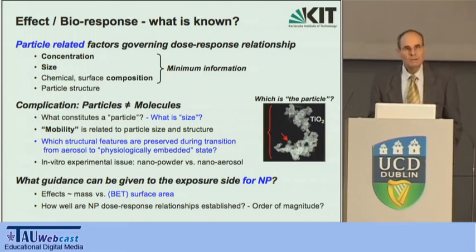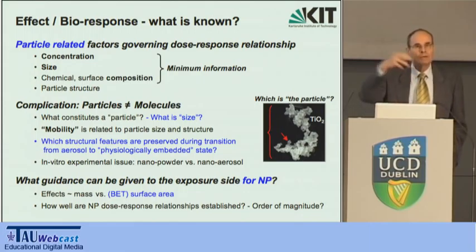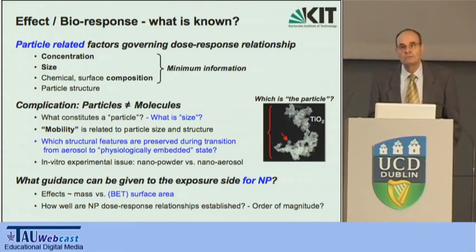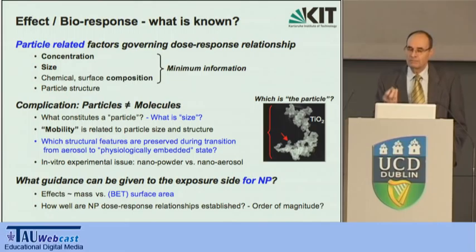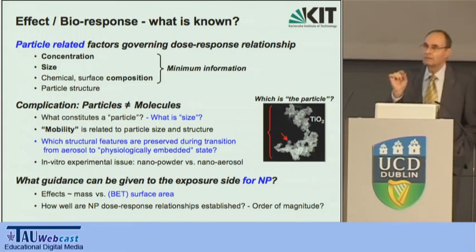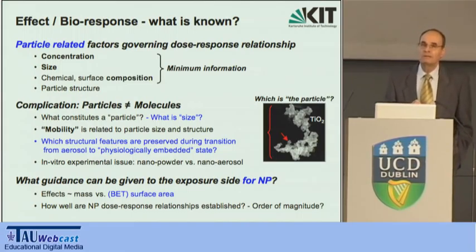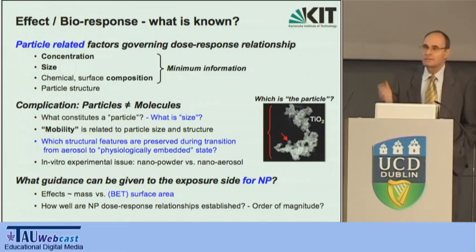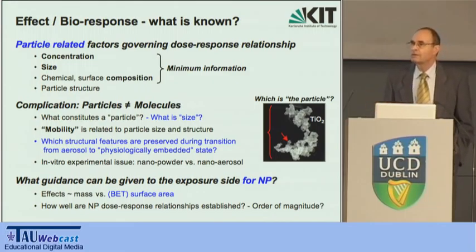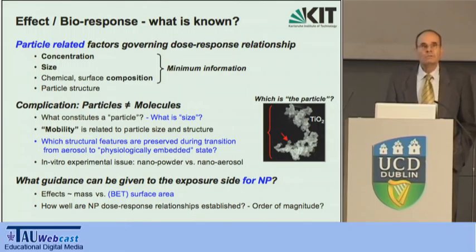Okay? So what is the particle size in that powder related to the transport properties of these particles in air in the aerosol form? In fact, what you will find very often is that, especially when electron microscopic information is available, is what an aerosol scientist would call the primary particle. The primary building block of this particle, where the red arrow points to, that's the particle size. And in fact, it's relatively easy to measure this particle size when you have a powder, because all you have to do is measure the BET surface area. And if you have a gram or so of that, that's something you can readily do. And from the BET surface area, you can calculate a particle size. But that's not the particle size which is transported through the air.